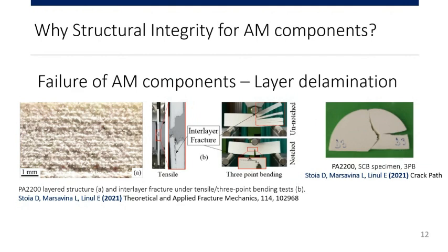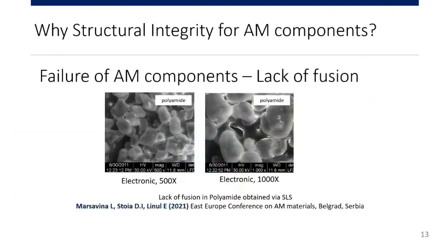Also, when we tested some semicircular bend specimens in 3-point bending with different orientations of the notch in order to look at mixed mode, we also sometimes have this delamination. So layer delamination is one issue.